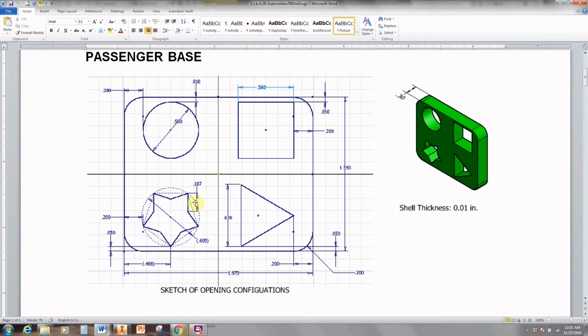And this picture here is from the T9 dimension drawings. And while it is accurate, this 0.187 dimension here can get students confused. It can kind of be a red herring, a misdirection. It's not a good way to make the star, I don't feel, trying to duplicate this 0.187.